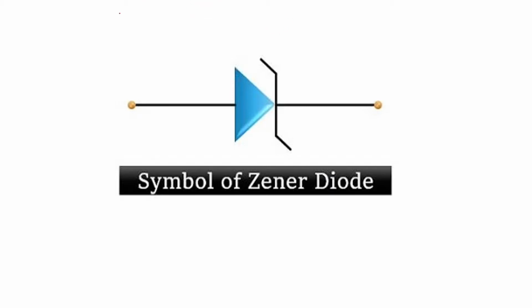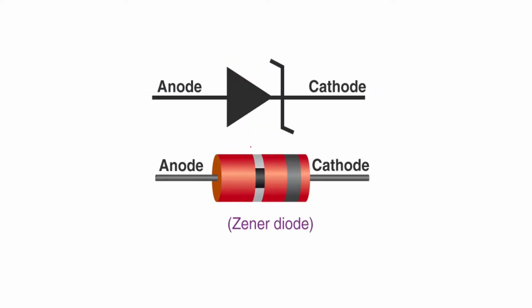This is the symbol of Zener diode. So here you can see it is a two-terminal device. The one terminal near the arrow is called the anode, and the other terminal near the bar is called the cathode. This arrow mark gives the flow of conventional current, and the bar is somewhat different from the ordinary PN junction diode. The difference is that the bar is bent here and bent here, so it takes the shape of Z, and this type of symbol is called the symbol of Zener diode.